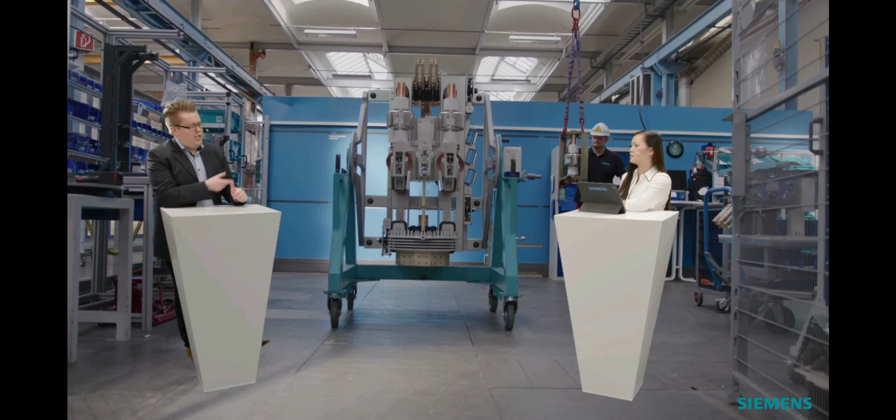This is the generator, also the transformer, the high voltage grid, and of course, mainly dependent on the out-of-phase behavior is the inertia constant of the generator. So if we have to calculate the out-of-phase current, we need to know actually everything of the whole system.